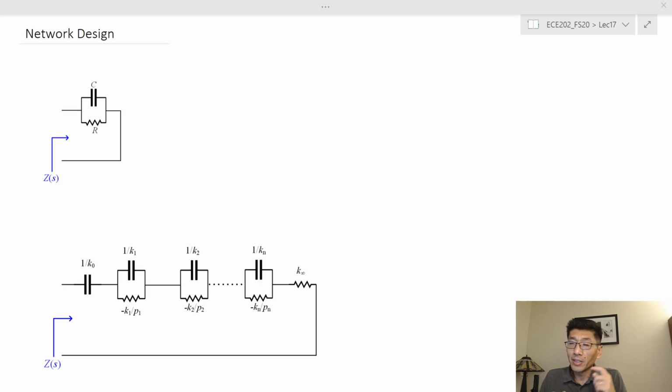So when we go into this, we are only at the very tip of the iceberg; we only scratch the surface by using the op-amp. If you don't use an op-amp, realizing the transfer function or the network function is much more difficult. We're going to use the op-amp, especially the inverting op-amp amplifiers and the RC networks. So we're going to start with the equivalent impedance of the RC network.